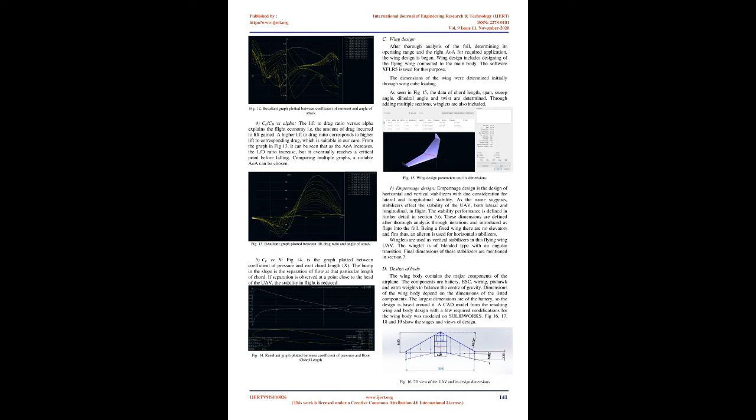2. Servo motors. The servo motors are used for the actuation of the control surfaces and the spoilerons of the wing. The control surfaces, or the ailerons, are used to maneuver the wing in the roll and the pitch axis. The spoilerons are flaps on the wing which can be opened to drain out water from the inside of the wing when the UAV egresses from water to air.